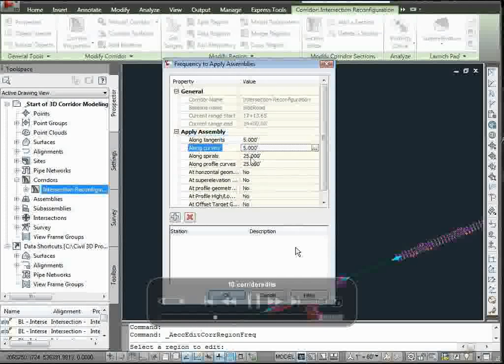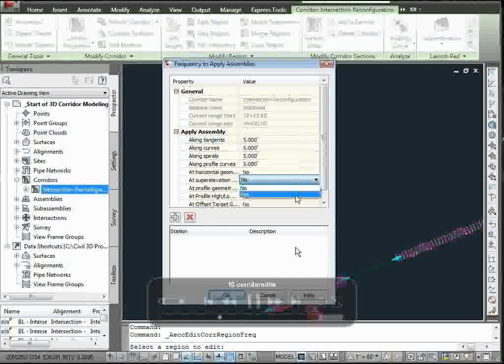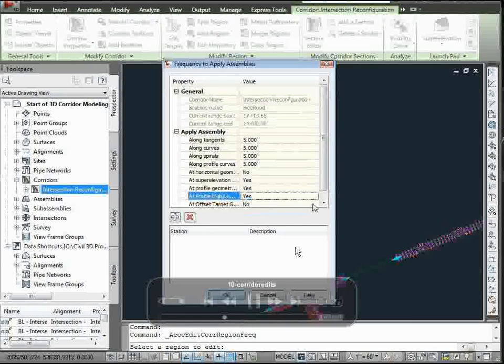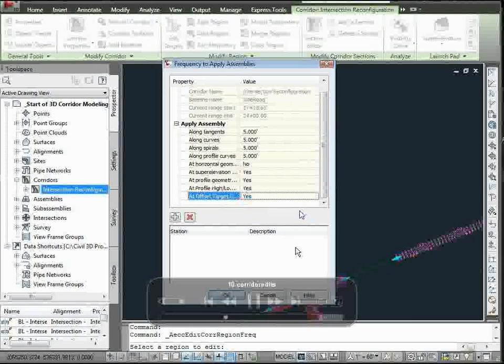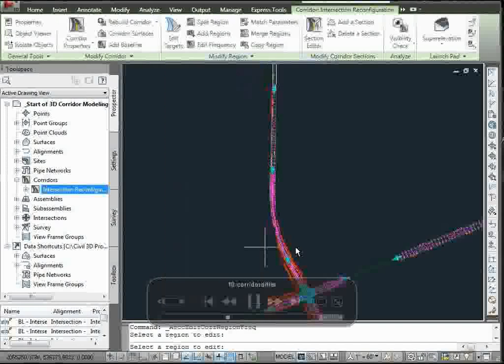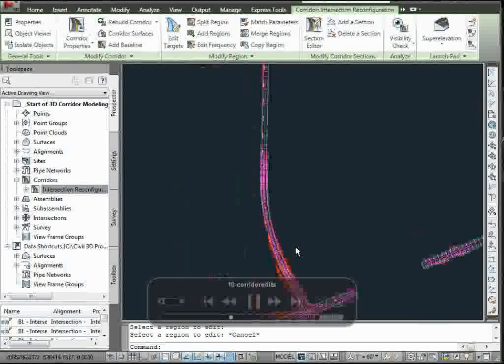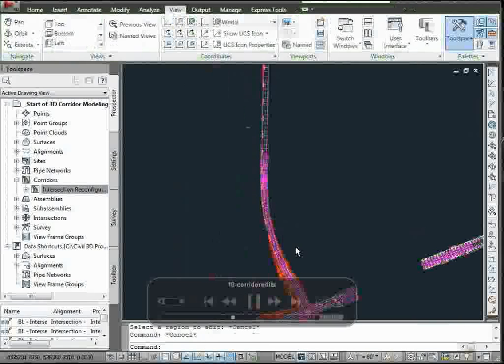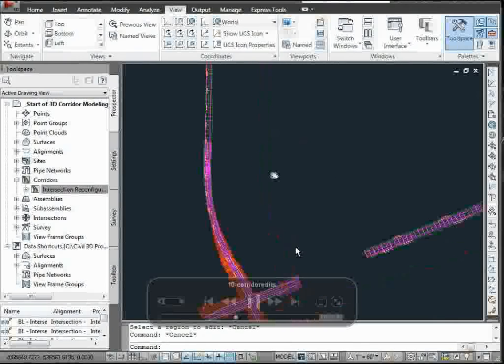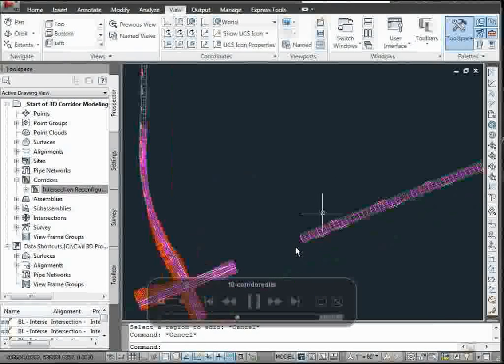And so we can densify this so we send more data out, and including super data, for example. The full super points, all surrounding the transition points, the profile highs and lows, we can pick up these additional points in our corridor so that when we go to machine control, we send all that out. And you'll see it here in a moment, a densified model that does not miss one piece of data that's needed to ensure we match the exact design. So that will let you come through.